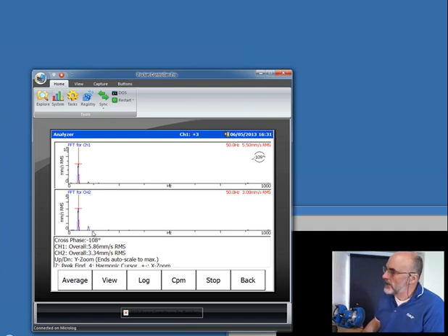There's a very little 2 times. More evidence that you've got unbalance. That reading is very stable. Again, more evidence that you've got unbalance. And in this case, the phase reading is very stable. You would be using a tacho type input for this, but that phase reading is nice and steady. So what you're looking at there is the absolute classic shape of unbalance on a rotating machine.